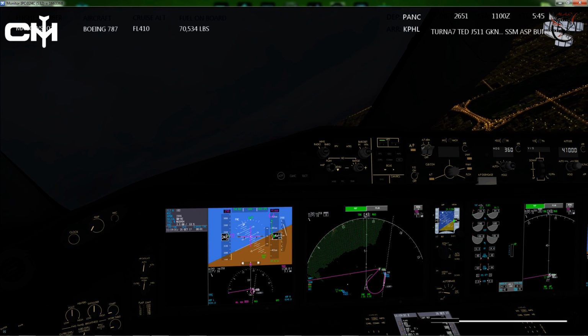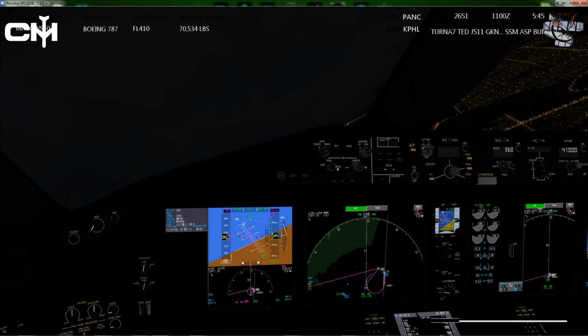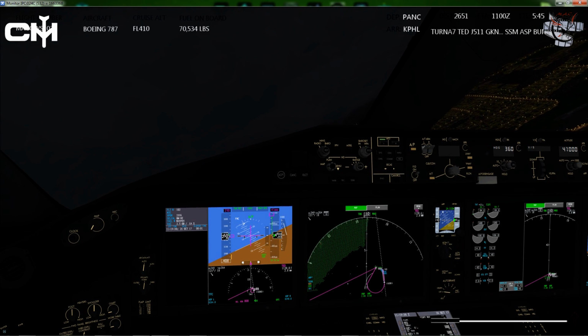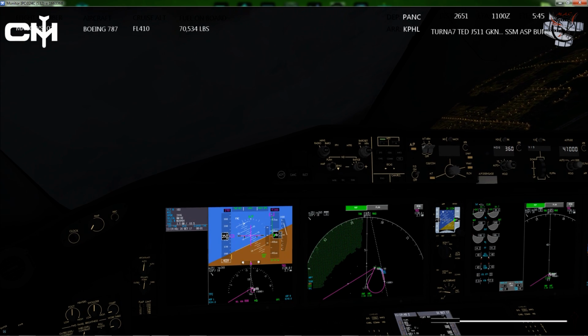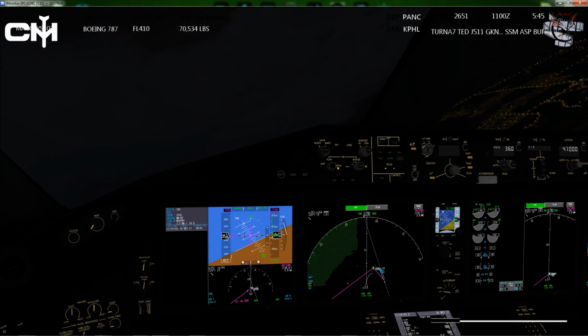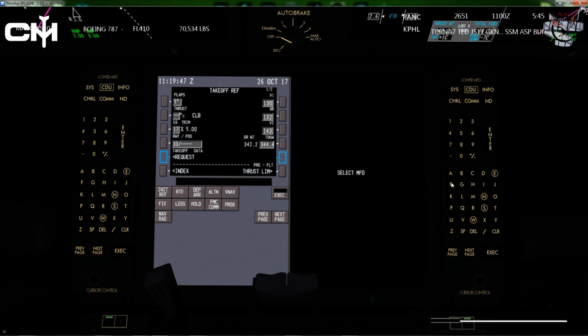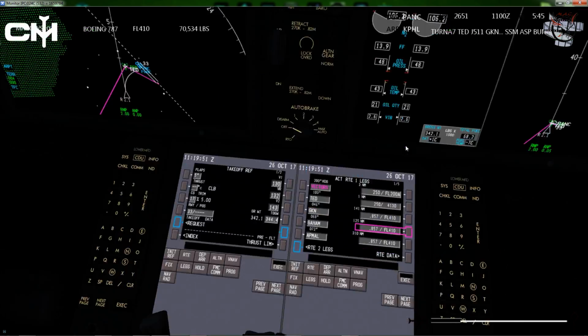Oh, I guess the flight attendant's talking back there. So gear is up, flaps are up, engine anti-ice is in the auto position, which is where we want it. And that is pretty much our after takeoff flow. Top down here, and for some reason this thing turned itself off. I don't know why. Put that on CDU.